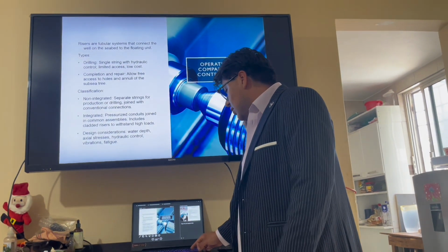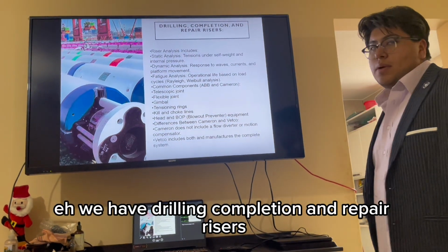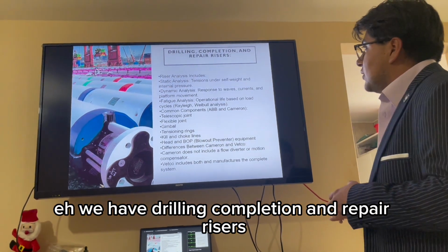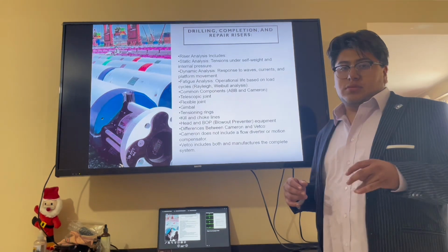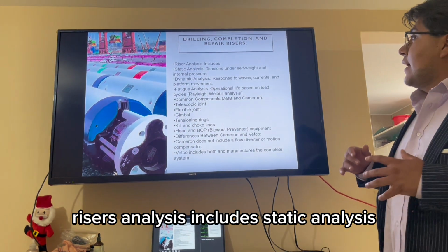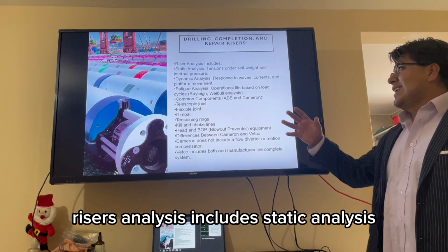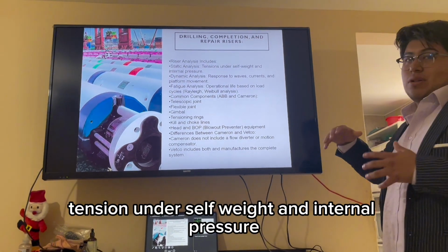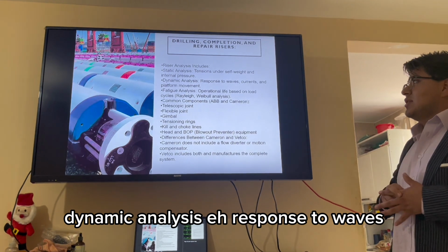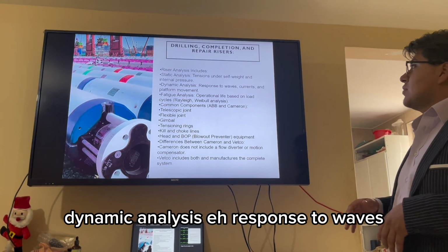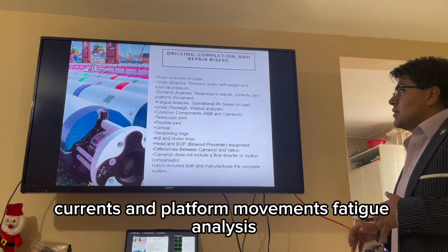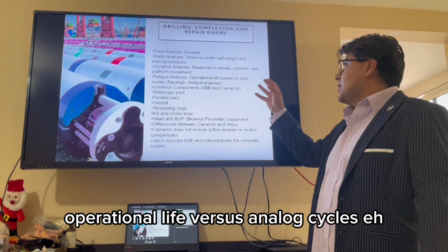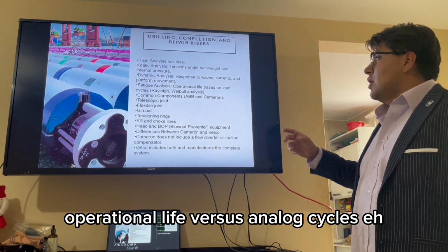The next, we have drilling, completion, and repair risers. Riser analysis includes static analysis, tension under self-weight and internal pressure; dynamic analysis, response to waves, currents, and platform movements; fatigue analysis, operational life based on load cycles.